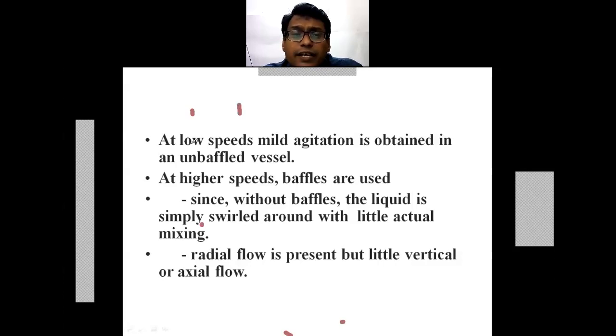At high speed, you require baffles, because without baffles the liquid will simply swirl around, with very little actual mixing.